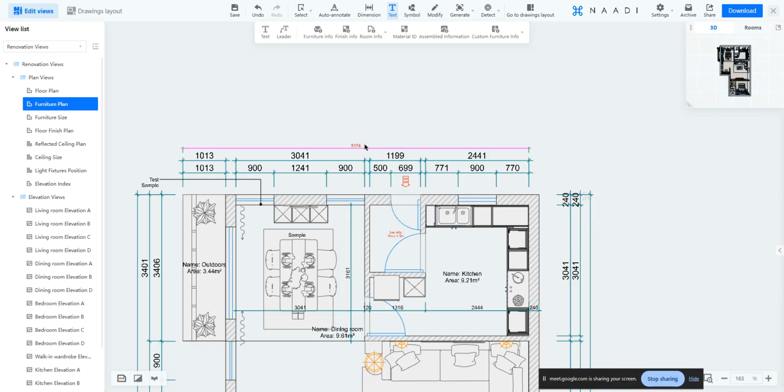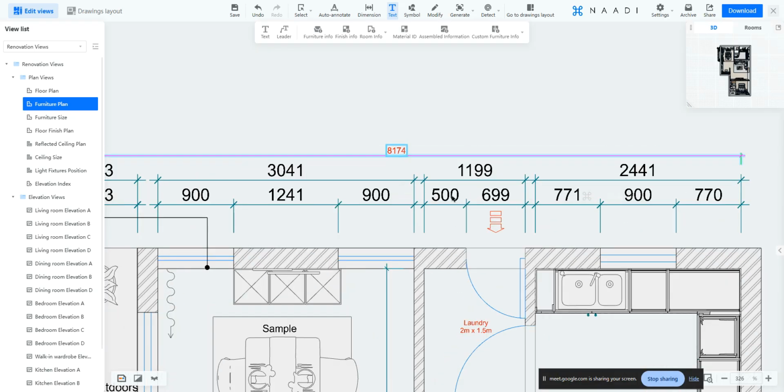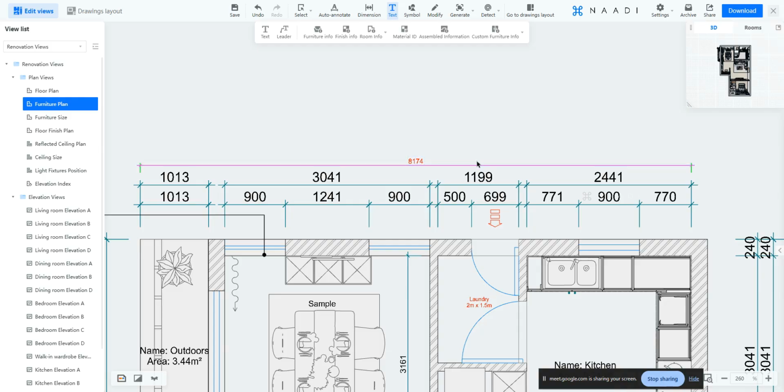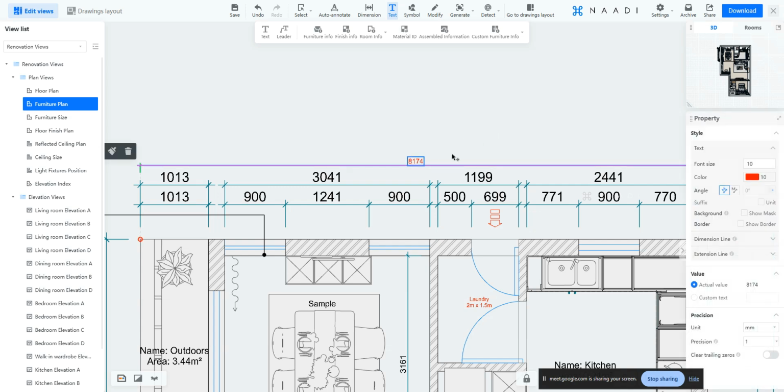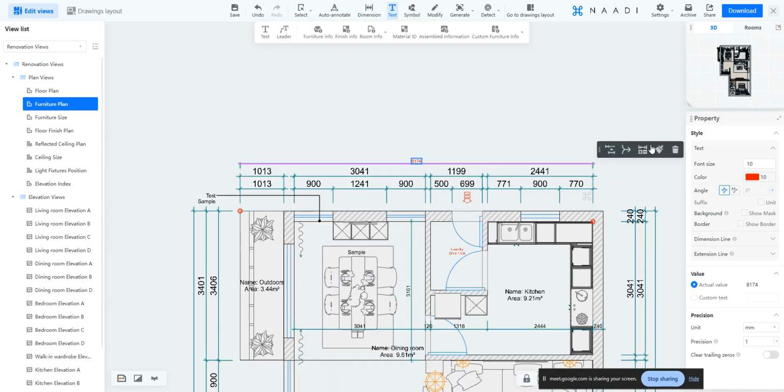Instead, if you have this kind of a requirement in CAD, what would be your general process where you edited one dim style? Now, if you want other dimensions also to go for the same dim style, in CAD, you have a practice of using your match property, right? You use match property to do it. Similarly, here we have something known as format painter. Okay, and the shortcut for that format painter is this. Can you see? M is the shortcut. It is there in the floating window. So once you select any dimension here, it will show some floating window. Yes, we even address this in your modeling as well in your respective foundation course.